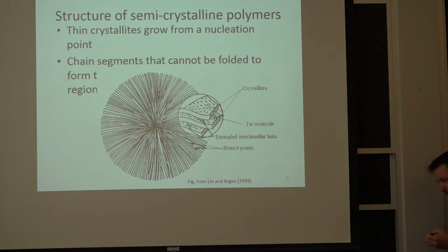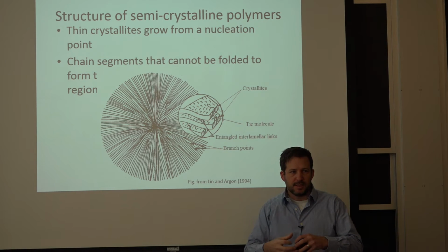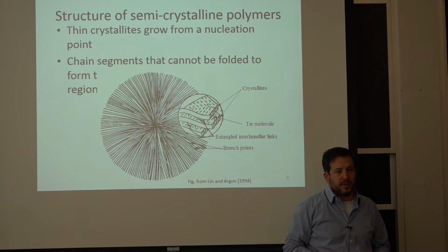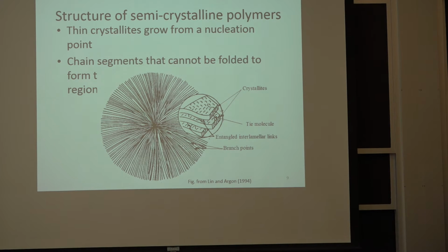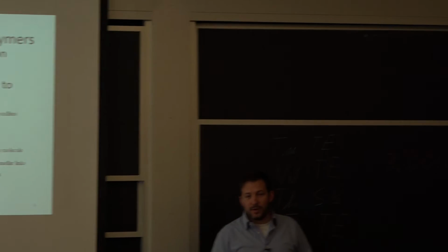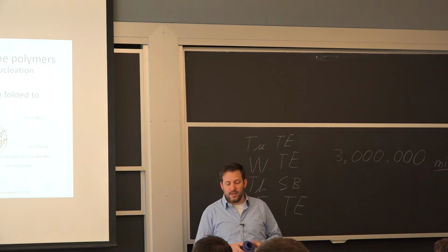Eventually, you get to a point where you start crystallizing here in the nucleus of this, and then it starts growing in different directions, just a little bit like a snowflake or a little bit of an ice formation on a piece of glass. It starts and then spreads in different directions. Now, sometimes if something is injection molded, like this piece here, it stays like that. This has the spherulite structures inside of it, and therefore it's fairly low strain.